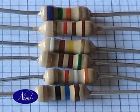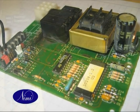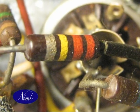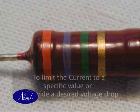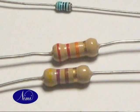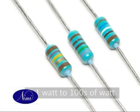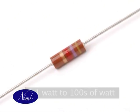Resistors are the most common passive component in electronic circuits. A resistor is manufactured in a specific value of ohms. The purpose of using a resistor in a circuit is either to limit the current to a specific value or to provide a desired voltage drop. The power rating of resistors may be from 0.1 watt to hundreds of watts.